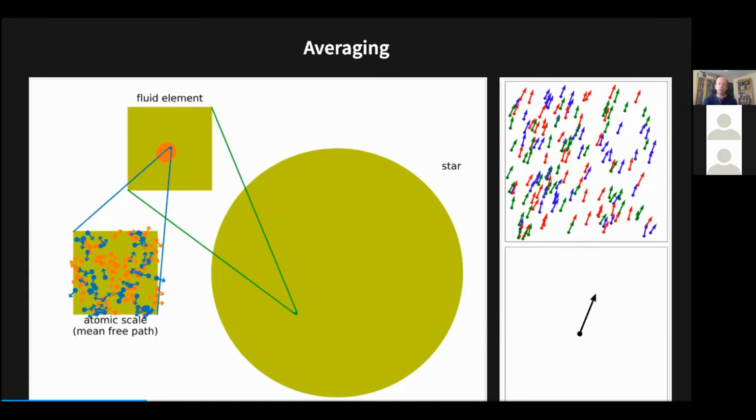So the fluid element description depends on the number densities, that is the number of particles within the fluid element divided by its representative volume, and also the velocity of this fluid element. There will also be additional properties of the fluid element that come out from the averaging process, like the internal energies or temperatures or entropies. So this averaging process gives us a small set of differential equations to solve.